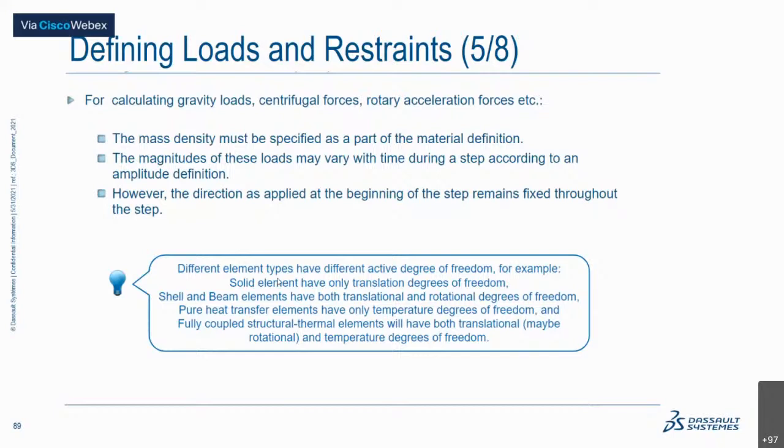Again, the magnitudes of loads may vary with time during the step according to the amplitude definition, but the direction in which you have applied them will remain constant throughout the step itself. So there's no change in the direction that will be happening.